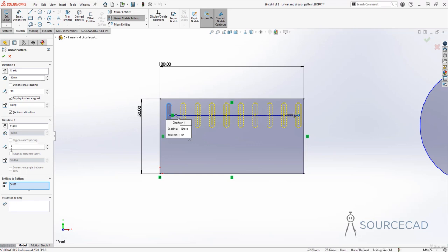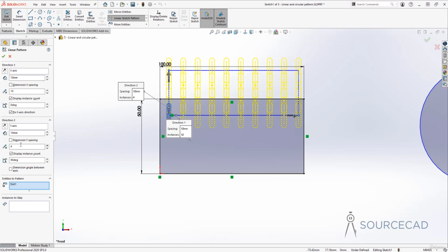Now the next option is number of objects along y. Currently it's 1, and that's why we don't have the gap, because with one object gap is kind of redundant. So as soon as I increase this number to, let's say, 2, you will see that an extra object is added and also gap is also added here. This becomes active. So here we just want 2 columns, but I'll just increase it to maybe 4 in order to show you how this is gonna look.